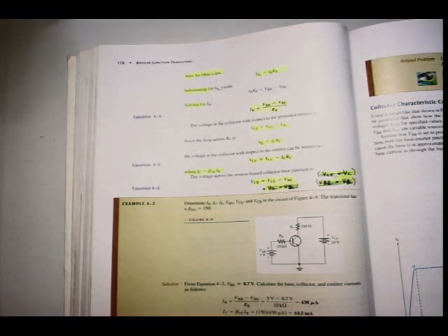Then substituting for RB, IBRB is equal to VBB minus VBE, and then solve for IB. So all that they've done here is they've combined the formulas. IB, and I've combined then Kirchhoff's law on top, VBB minus VBE to determine the voltage drop over VRB, and below the line RB, which gives me my Ohm's law. The voltage at the collector with respect to the grounded emitter, remember VCE.